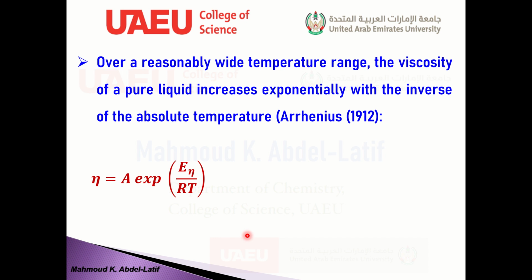Okay, another parameter is that the viscosity depends on the temperature. Generally speaking, the viscosity of a liquid decreases with increasing temperature. Over a reasonably wide temperature range, the viscosity of a pure liquid increases exponentially with the inverse of the absolute temperature.